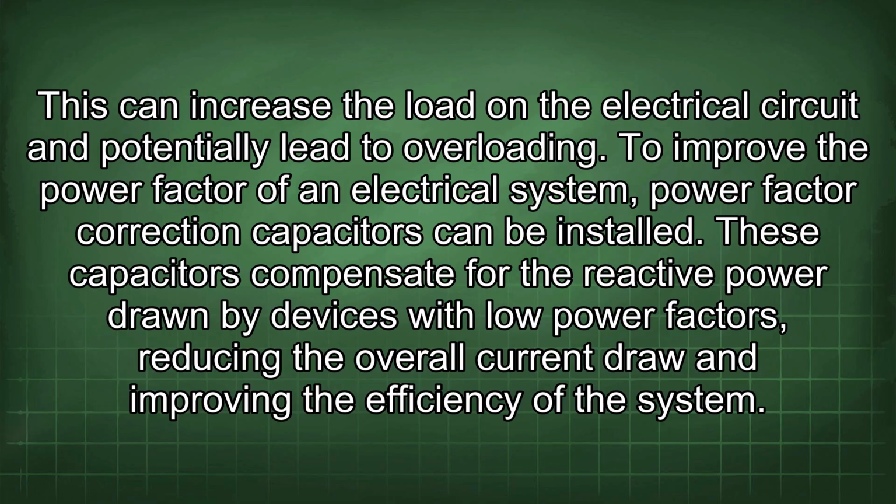To improve the power factor of an electrical system, power factor correction capacitors can be installed. These capacitors compensate for the reactive power drawn by devices with lower power factors, reducing the overall current draw and improving the efficiency of the system.